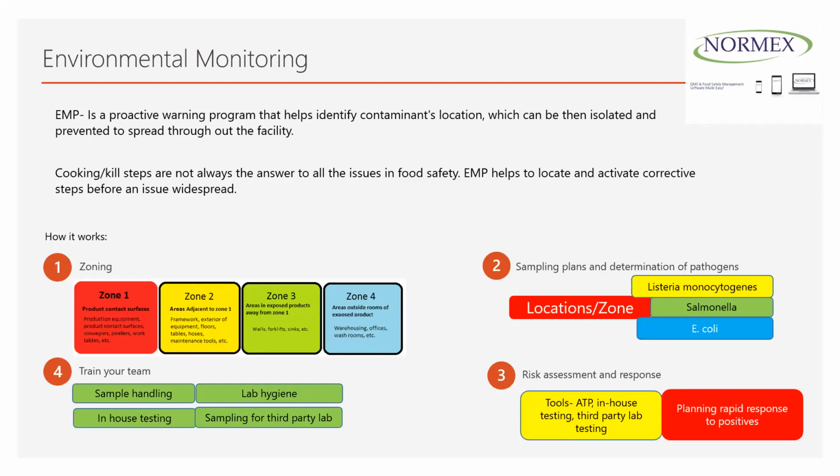For example, you have cooked lasagna, but before packaging, you're exposing it on a conveyor belt on the line. Then you require an effective environmental monitoring program to determine whether contaminants or pathogens could enter between that cooking step and the final packaged product.